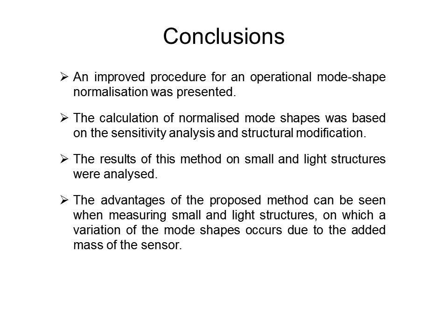The comparison proves that the method proposed in this study gives better results than the ordinary mass change strategy because the sensor's additional mass is cancelled and the mode shapes are scaled correctly. It is advisable to use the proposed method when the mass that is added to the structure by the accelerometer is not negligible. The measurement of the excitation force is not needed, which makes the experimental investigation even more straightforward and easy to perform.